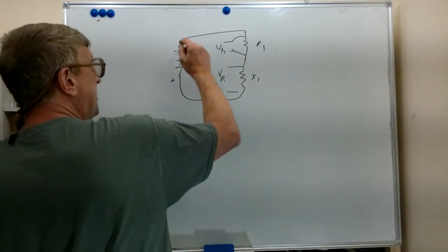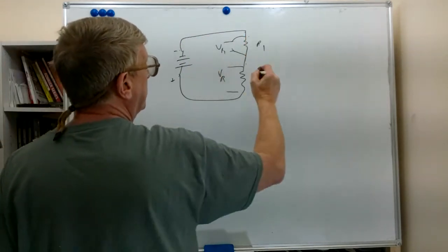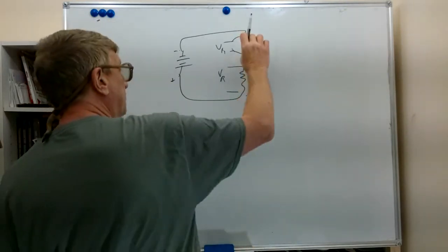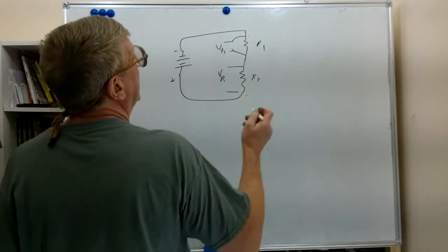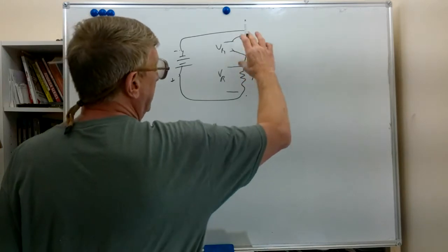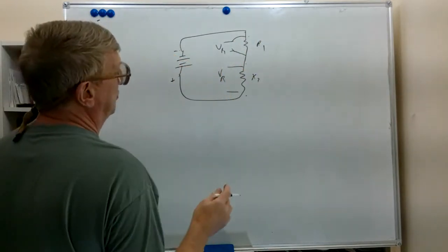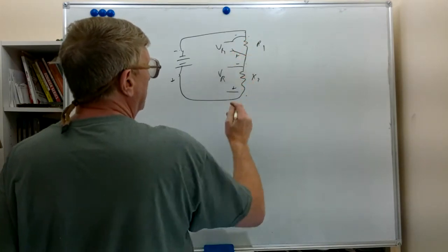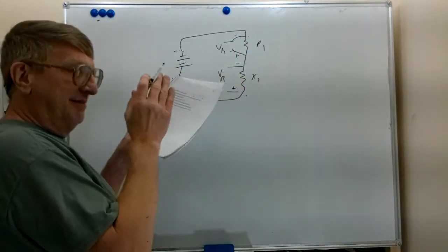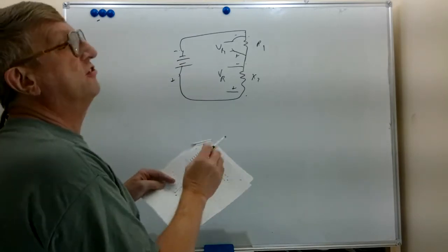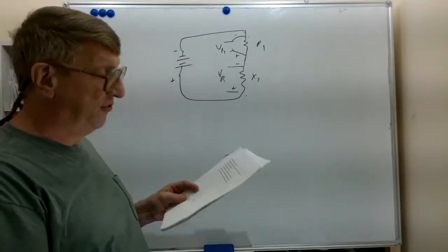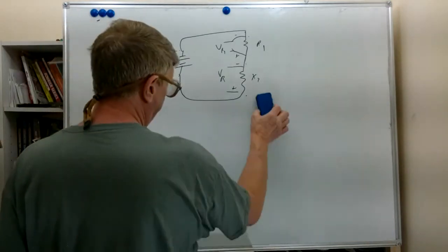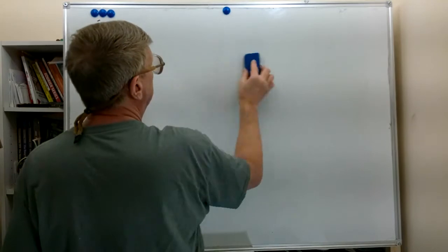If you look from the top of R1 to the bottom of R2, the total voltage drop, the sum of those two voltage drops, is that much less than the supply voltage. So that's why we call it a drop. It's like that voltage appears there, there's less voltage left to appear on the rest of the circuit as you move your way around. I think that's a good way of describing it.